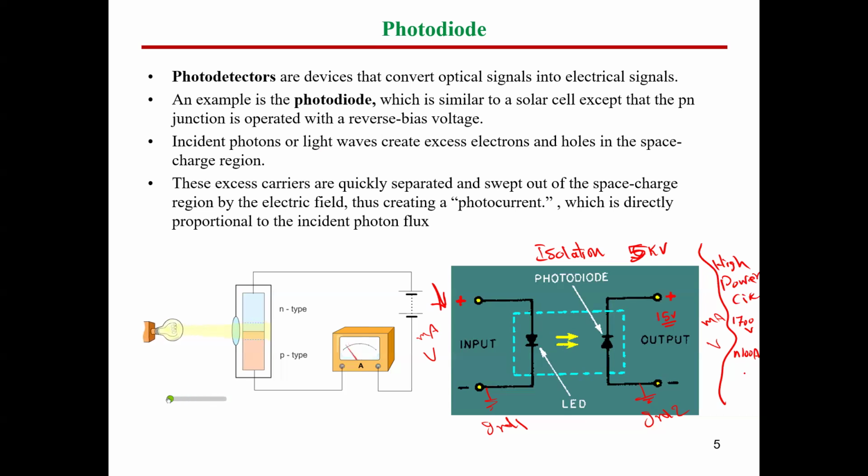And this is relatively high power compared to the microcontroller. So the benefit is whatever happening in the high power side here will not affect the microcontroller side. So if you have something like a short circuit or anything in the power circuit here, you will protect your power circuit by any type of protection, but at the same time, we don't need our microcontroller to be burned. So the operation depends on this optocoupler, which will be broken in order to avoid breaking or damaging the digital controllers used.